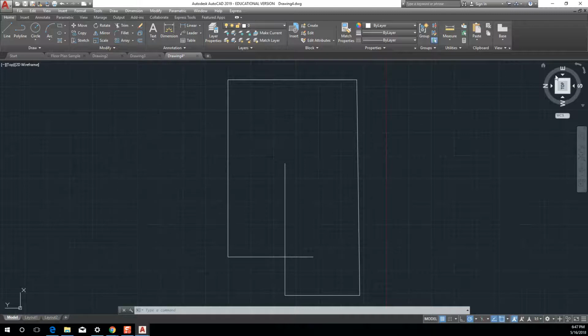She didn't really need to navigate that way. She was drawing lines like this in her top view, but what she wasn't realizing is that when she drew these, in the top plane it looked like that. But if I looked at it from the side in a 3D view, it actually looked like that, right? So this line was here, and this line was way over there, instead of being flat in that direction. It's called being non-coplanar. Does that make sense?